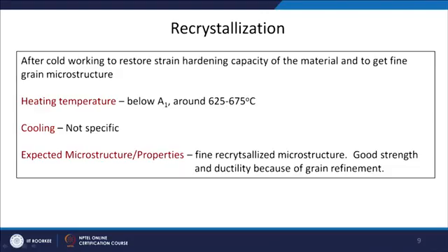Then there is another process called recrystallization; again you will be able to understand more clearly when we go to mechanical properties. After cold working, to restore the strain hardening capacity of the material and to get a fine grain microstructure, this recrystallization treatment is given.